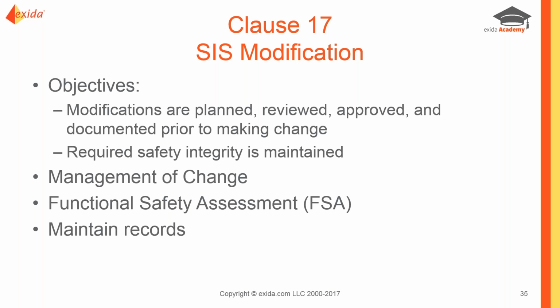The modification phase, the main issue there is that if we have any modifications that are planned, you want to go through an appropriate management of change process. In essence, kick it back up to the appropriate location, usually starting again with hazards assessment, and start the life cycle all over again for those modifications, and make sure that the integrity is maintained throughout the entire modification phase and that we don't let any new risks slip in.